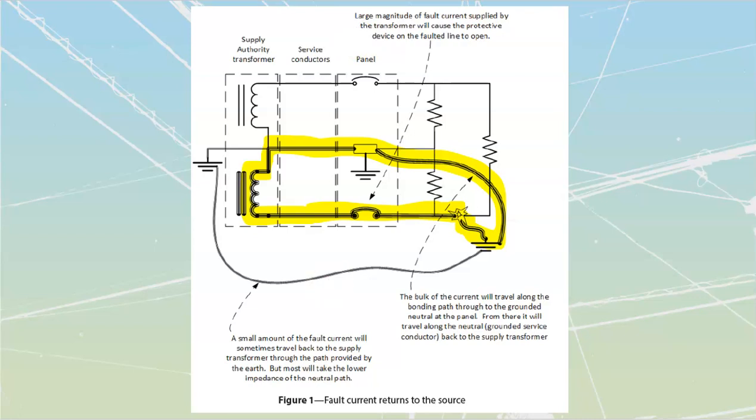We saw that this path over here, the actual path that goes from Earth all the way up the grounding conductor over here, does not carry a lot of current. So as a result of that, we get away with having this thing as a number 6. We just looked at that in the previous learning task. But this path that we have over here, our bonding path itself, is going to have to carry all of the fault current back, which means that it's going to have to be a fairly large path in order to be able to carry large magnitudes of current.